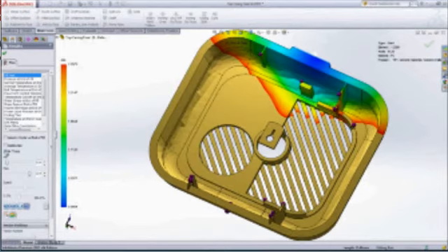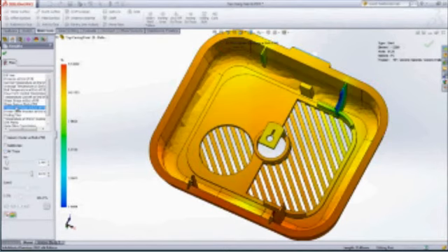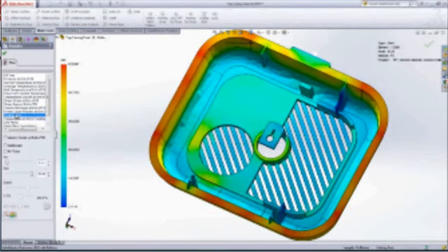We can also look at some of the results such as air traps. These are places where the air is inside the mold cavity before it gets pushed out. They can also indicate where the mold manufacturer or the mold designer should put the ejection pins to facilitate the air to escape. Other result plots also indicate a substantial cooling time of more than 60 seconds due to the thick area of the part. This will drastically affect the number of parts you can manufacture per hour and the overall cost of the part. Another critical information for mold designers and manufacturers.